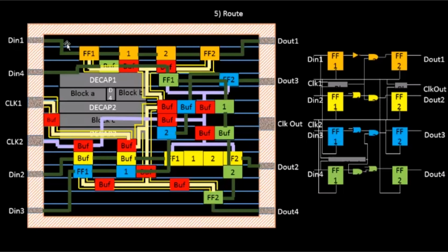You need to route the design and maintain the existing timing scenario. For example, we did a timing analysis in the previous stage, the clock tree synthesis stage. The route stage should make sure that while routing the design, we do not deteriorate the existing timing scenario. We should not get worse than that. If we can improve it, we can, but we should not go worse.